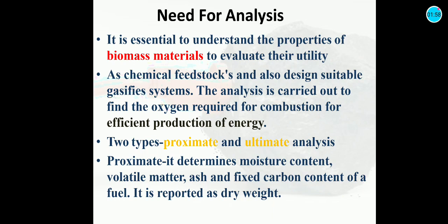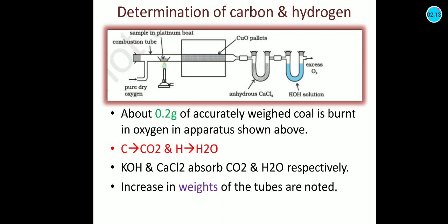Two types: proximate analysis and ultimate analysis. Proximate analysis is to determine moisture content, volatile matter, ash content and fixed carbon content of a fuel. It is reported as dry weight.